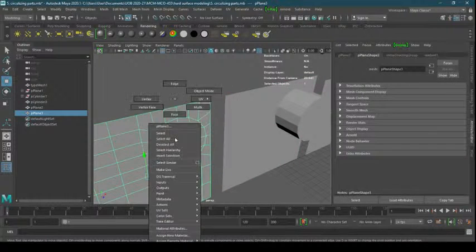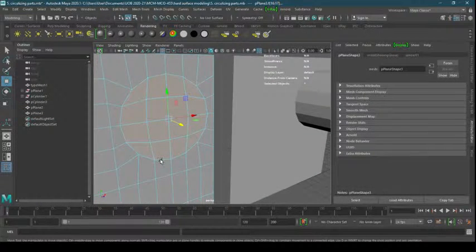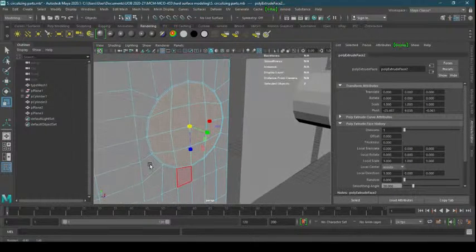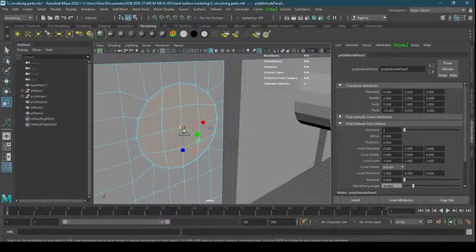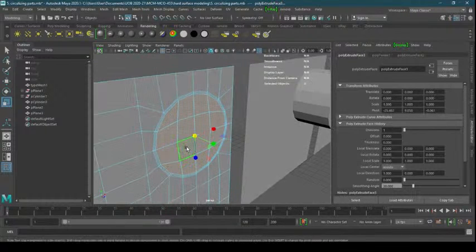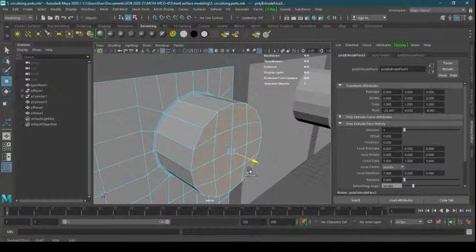Now what I will do here, I click faces. Here I will press R for scaling, press shift, reduce the size of it. So I will have this, I think small is enough. Okay, if I want more, I can again press shift, and this will create more division. So I can keep on doing that if you want more division, but I don't want that. Now W, I can have now extrude.